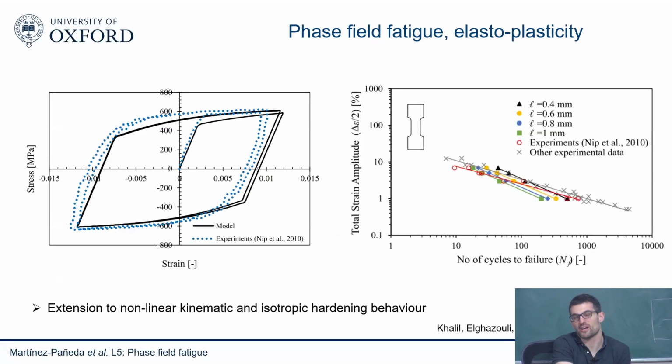So everything so far has been linear elasticity. Of course, plasticity does play a role in metals. It doesn't play that big of a role in Paris law behavior. There, things are very small scale yielding, so the plastic behavior is very localized at the crack tip. So you can do the test. You can run a simulation with different strain hardening exponents, for example, and you will see almost no effect in the Paris law regime. But it does play an effect in other situations, of course.